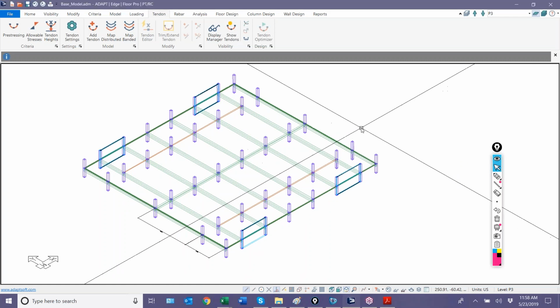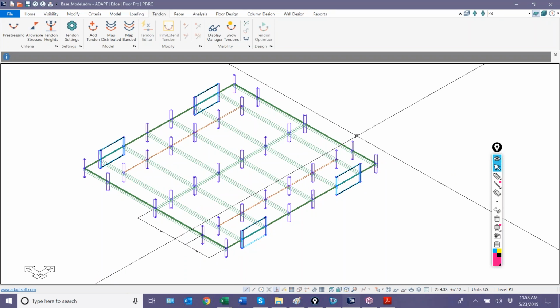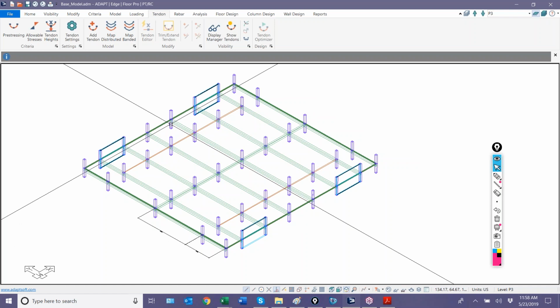I've shared that, and today we're going to continue with part 2 of the one-way slab and beam example that we had set up last week. Just a few announcements. This is related strictly to gravity only design, so we're going to talk today about generating the strips in the one-way slab direction, and then also add post-tensioning to the beams and also the slabs, and then we'll go ahead and process the design of the slab and beams and look at some results for this example.